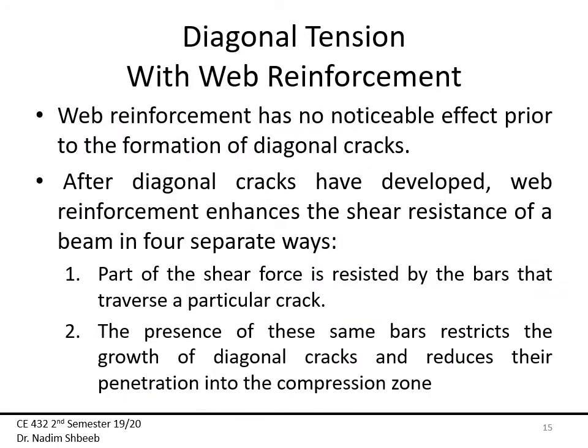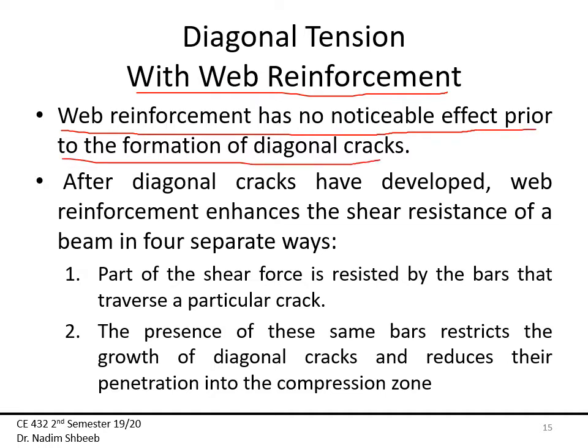So what happens when I put web reinforcement? Well, the first thing that we should know is that web reinforcement has no noticeable effect prior to the formation of diagonal cracks. That means that in the experiment, it was noticed that if we measure the stress in those shear reinforcements, there's actually zero stress.